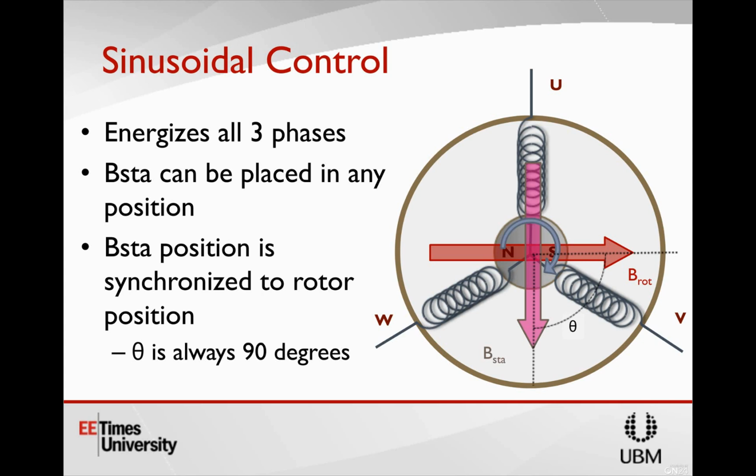Motors that have bigger inertia and more mass to turn make this technique very difficult, because you have to apply a lot of current to drag the rotor into alignment, drag it around with you, and accelerate it up. It's also highly dependent on the rate of acceleration, which works in concert with the inertia. Obviously, the faster you try to accelerate, the more current you have to use to keep your motor rotating. That can be tricky to balance.